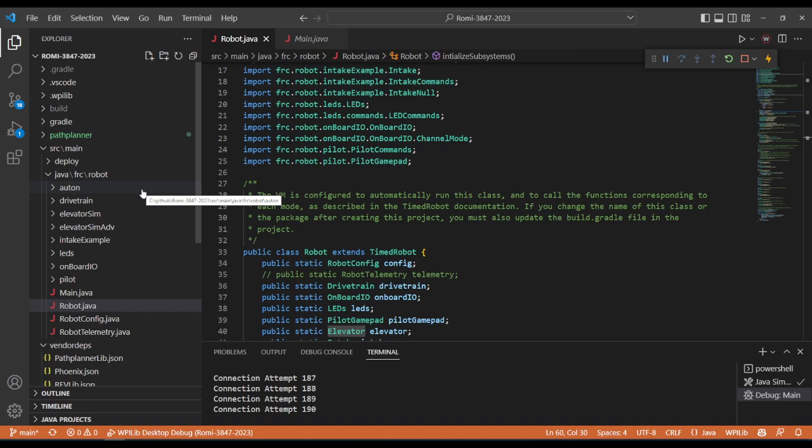So there should be, I think, 5 right now. My guess is that we'll have somebody responsible for autonomous, so that's mostly the path planning and actually making sure all of our auton routines work well. Someone specifically responsible for swerve, because there's quite a bit of tuning and programming that goes into just making sure the drivetrain is working well, and that kind of feeds into the autonomous working well and every other subsystem working well. If the drive isn't working, nothing else does. They'll probably also be somewhat responsible for the pilot's controller, making sure the control scheme makes sense.